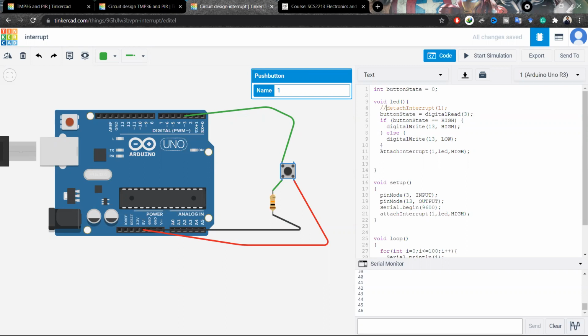But the scenario is this piece of code is a very critical thing. So we know that we should completely execute this function, right? That's why we are putting this detach interrupt. Otherwise, if you didn't put the detach interrupt,